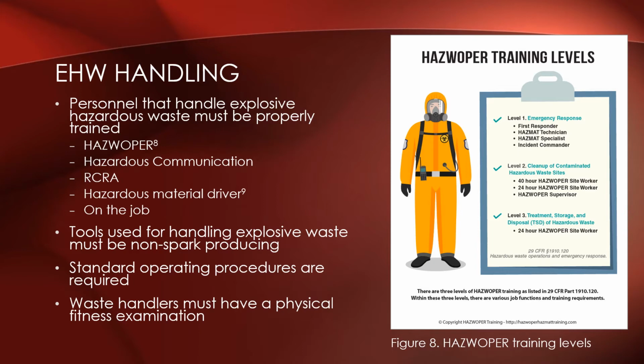In addition to the training requirements for explosive waste handlers, tools used for handling explosive waste must be non-spark producing. Standard operating procedures for handling, treating, and storing waste are required, and all waste handlers must have a physical fitness examination and be in a medical surveillance program.